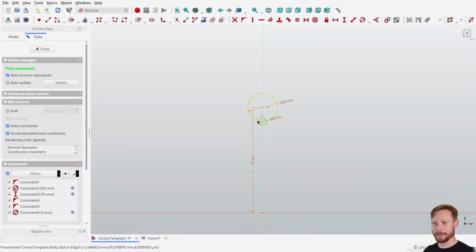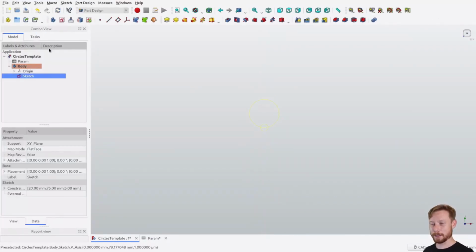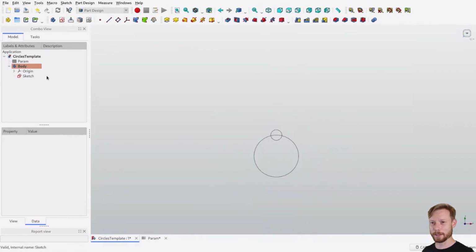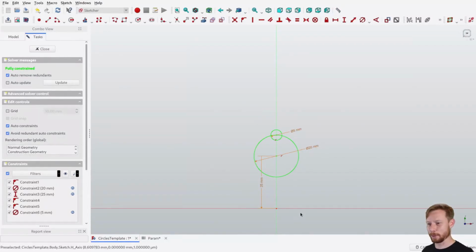Well, it's done everything that I said to. So it's still attached to that center X line. It's still attached to the outside of that circle. The issue is the order that the sketch solver will solve things and the order that I put constraints in and so on. So it's best to just follow my rule, which is use absolute references wherever possible.